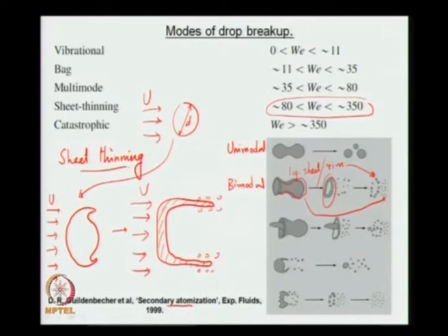This is more like our high Weber number diesel or jet atomizer. And so, I create this thin elongated liquid sheet that breaks up into finer drops, which are shown here, and a few large drops from the breakup of this disc-like structure.